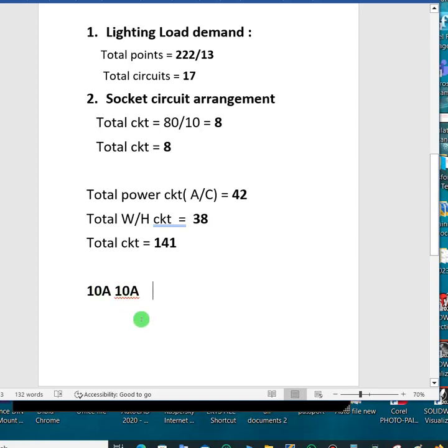That is for the lighting circuit. Then for the ring circuit, we are going to have 30 amps spare. As for the air conditioner, with our calculation for the air conditioner, we're going to also have 15 amps spare. Then for the water heater, based on our previous calculation for this breaker size, we also have 15 amps.